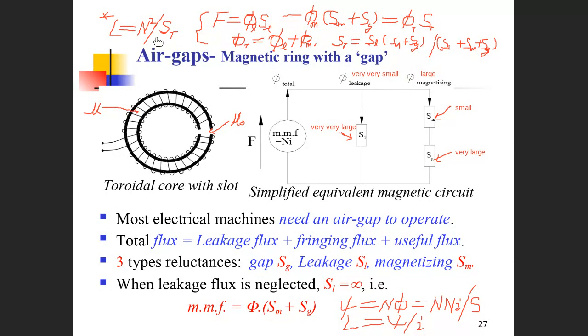So in practice, we're using this one to determine the inductance of a given coil, a given magnetic circuit. Remember these points. The key in the circuit will be determining the reluctance. To determine the reluctance, the key is to determine each component's permeability.